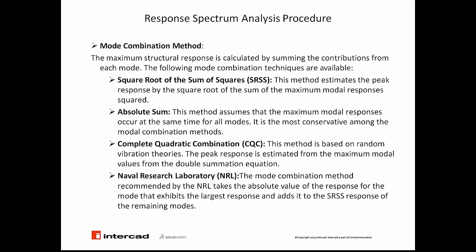But one thing for sure, what we understood up to here is we have a system, and the system has its damping ratio, stiffness, and mass. The peak response of the structure to a base excitation is what we are going to apply and measure, and then for different modes of frequency, those peaks need to be added together to get the new response. That is what is required in response spectrum analysis here.